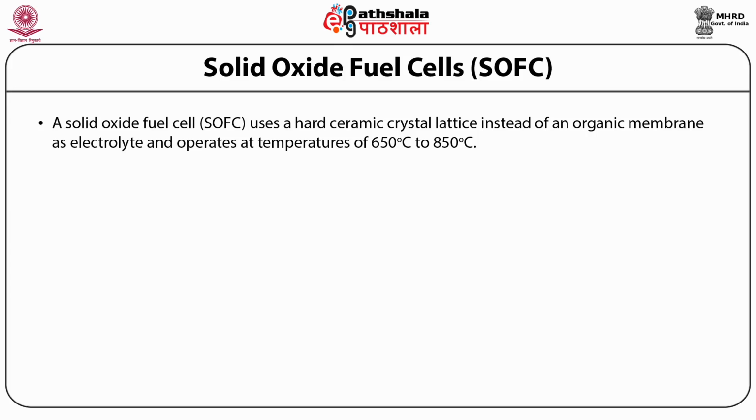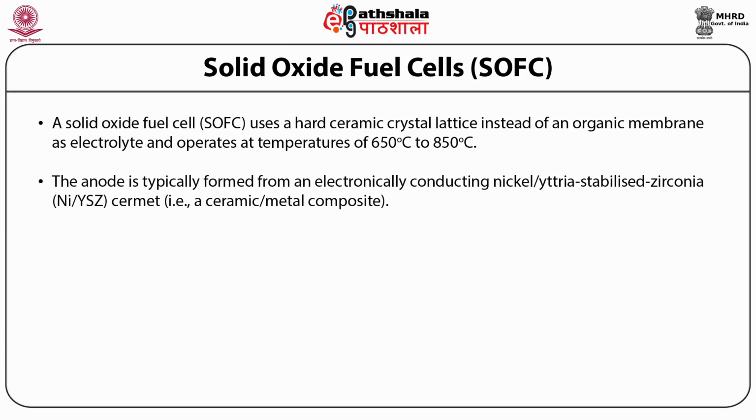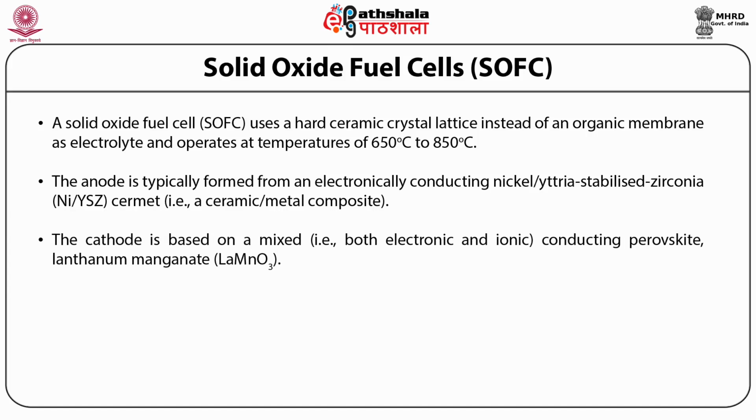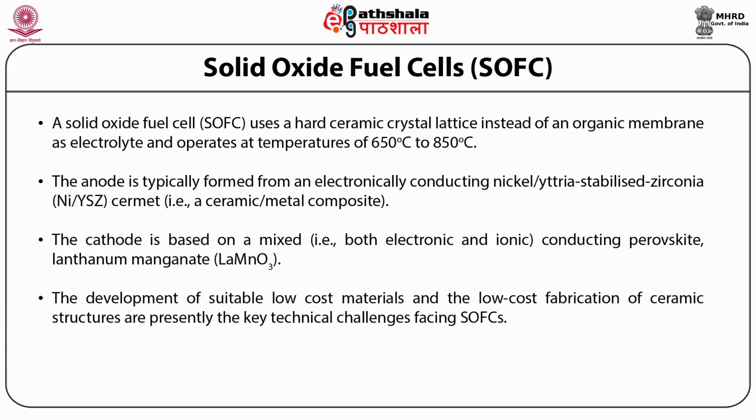Today's technology employs several ceramic materials as the active SOFC components. The anode is typically formed from an electronic conducting nickel yttria stabilized zirconia cermet, that is, a ceramic or metal composite. The cathode is based on a mixed electronic and ionic conducting perovskite, lanthanum manganite. Yttria stabilized zirconia is used as the oxygen ion conducting electrolyte. The development of suitable low-cost materials and low-cost fabrication of ceramic structures are presently the key technical challenges facing SOFCs.